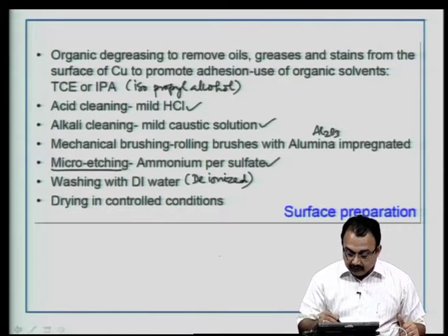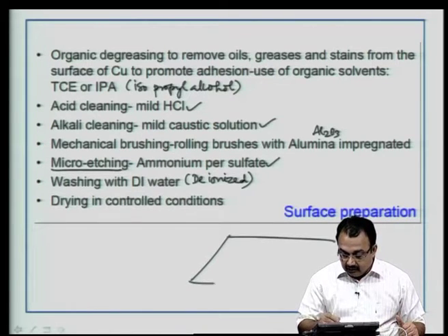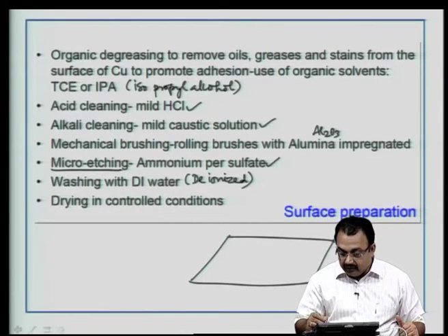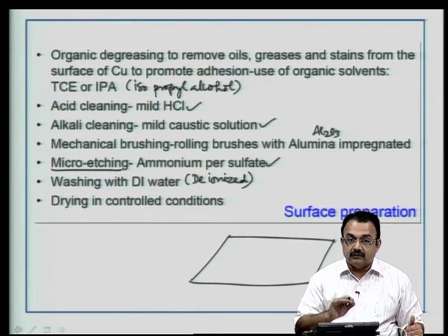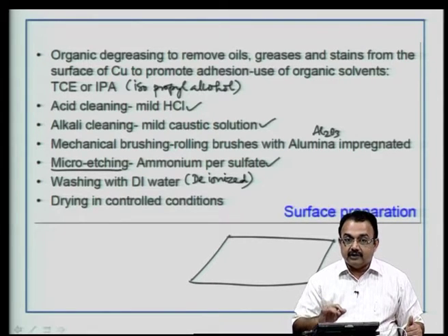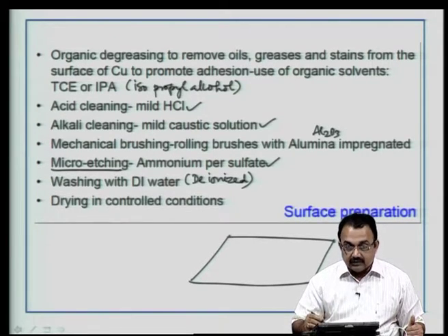The need for making the copper clad surface rough. When you get the copper clad laminate from the manufacturer, generally the surface is very smooth. If you use it as it is, your adhesive in the photoresist is not going to stick onto the surface.